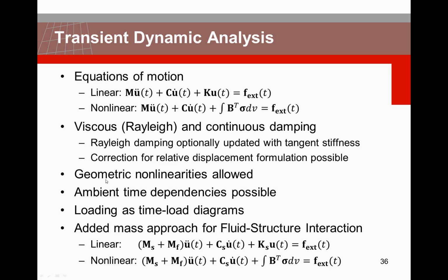The next thing that you can do in a transient dynamic analysis is that you also apply geometric nonlinearities next to physical nonlinearities. It also works to include ambient time dependencies, say temperature or concentrations, pressures.